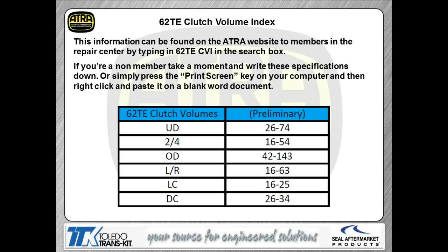That's good. Other changes between the 41 to the 62 TE is you'll notice that the solenoid block or body looks very similar to an RFE, especially with the 23-way connector. So that's the first thing you're going to notice there. Now, we've added a TCC solenoid, which they refer to as the EMCC. It's a variable force solenoid. It's electronically modulated converter clutch.